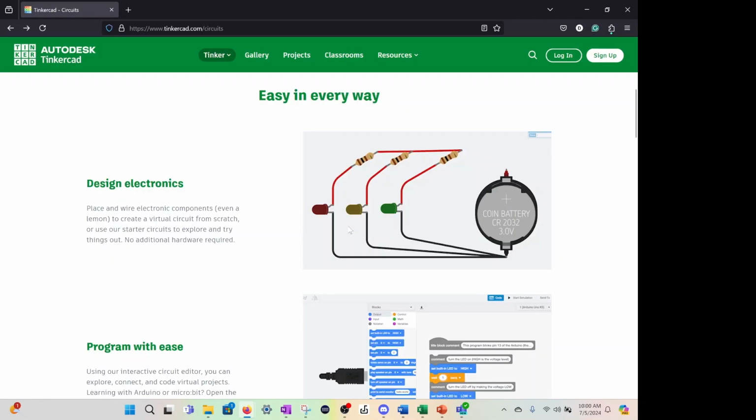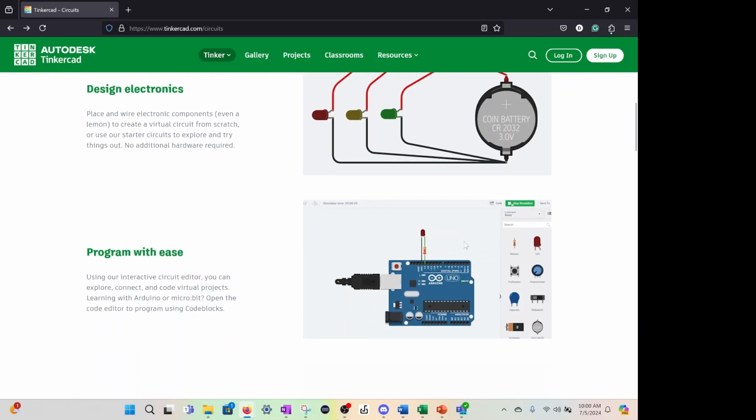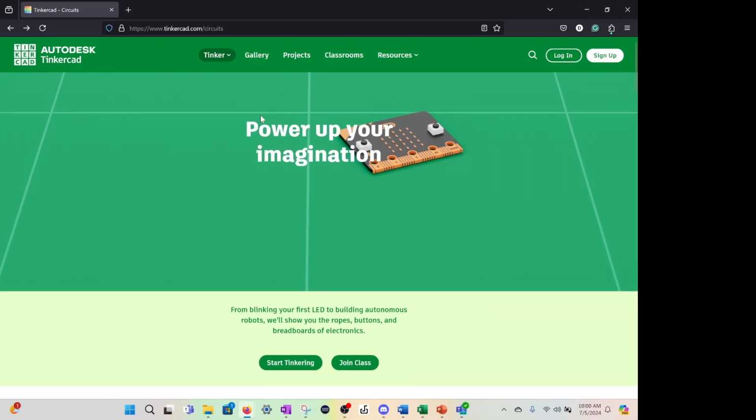It's a drawing program or a sketch program where you can put LEDs, resistors, wires, and hook them up to a system. You can see what the Arduino circuit diagram would look like. And you can actually click and have it run and see if this would actually work without having the physical components. It's awesome. Highly recommend downloading Tinkercad, checking out the circuits, and playing around with it before school starts.